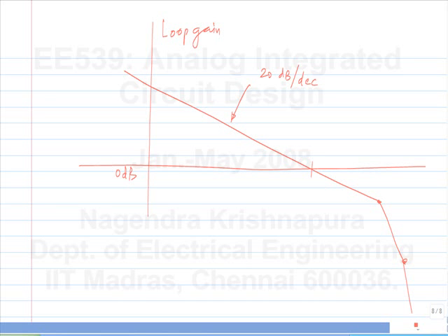Okay. Now we also know that if the effect of poles is too much and you have facility to add a zero somewhere, you can do that to cancel the effect of the pole. Okay. Because each pole delays the ramp response, each left half plane zero advances the ramp response. So you can use that to some beneficial effect. Okay. But if you have only poles, this is the type of picture I would want to see. I want a first order roll off up to unity gain and a little bit beyond it, and all of the parasitic stuff should be happening there. Okay.